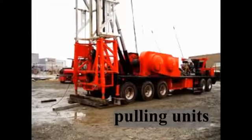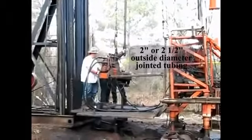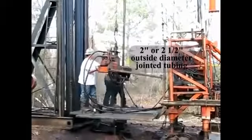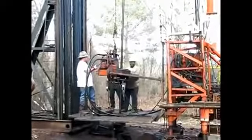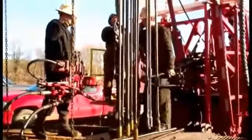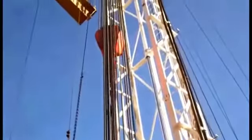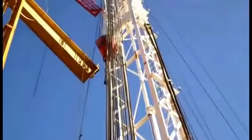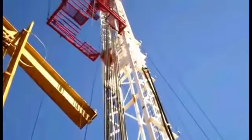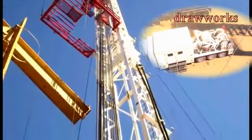Pulling units. These mobile onshore units using 2-inch or 2 1/2 inch outside diameter jointed tubing operate as a work string. These pulling units are multi-purpose machines because they can be used for routine pulling of rods and tubing as well as for major workovers. Notice that the drawworks here is smaller than those used on drilling rigs.